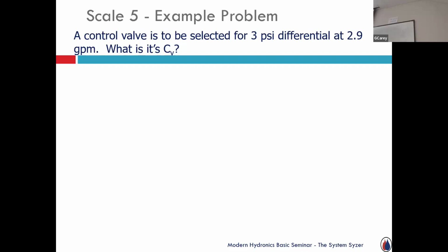Okay, I'm sorry. Control valve authority. Control valve authority. All it's stating is, when a control valve is modulating, open or close, it's not just set point, open, close, I'm satisfied, I'm not. When I'm modulating, the reason I'm modulating is I'm trying to control something. Maybe the discharge air temperature on a makeup air coil, hot water leaving a heat exchanger, whatever it is.